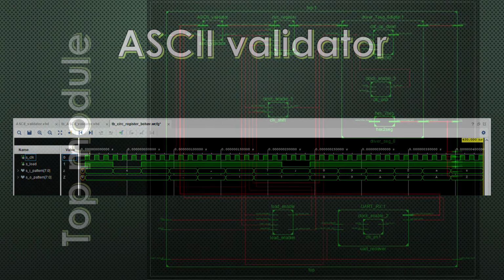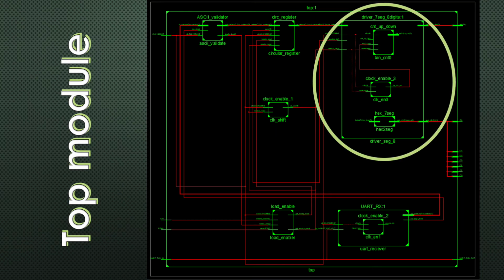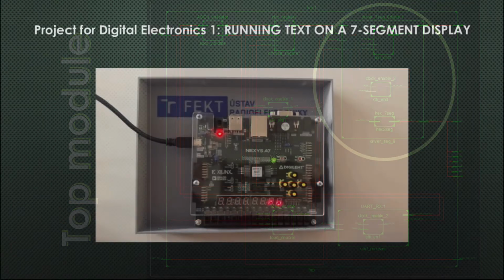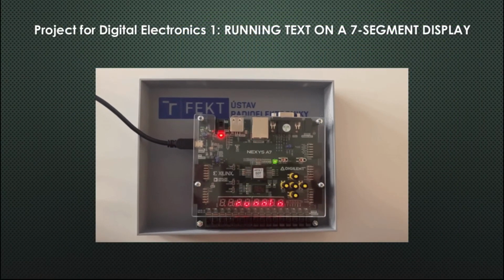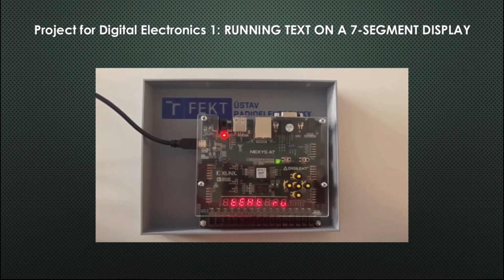The biggest module in the top, our display driver, takes the input value, shifts all the previous ones to the left, and discards the leftmost one. This happens only when the enable signal is present. Then the input value is converted to 7-segment code and is displayed on the 7-segment display. Just like here, when no value is currently being received, it only multiplexes and updates all 8 digits.